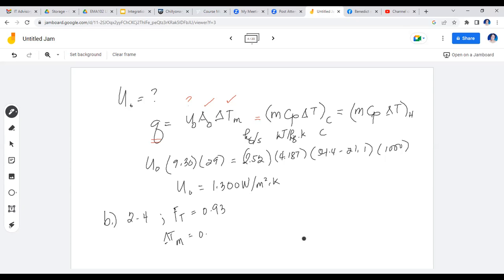So I'll just place it there and then place this as the comma. 1,300 watt per square meter per Kelvin. So I missed that this one is in kilojoule per kilogram Kelvin. I thought it's just joule per kilogram Kelvin. Okay, so there's a need for you to homogenize your units in the left side and the right side of the equation. Is that okay now, Kyle?